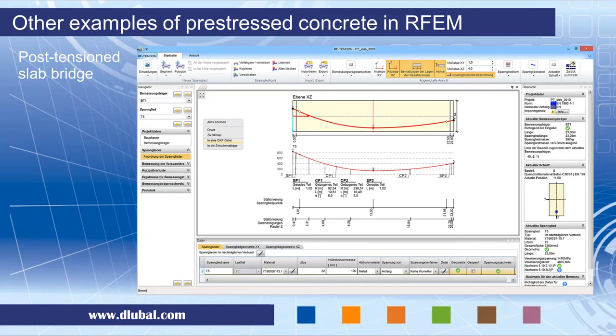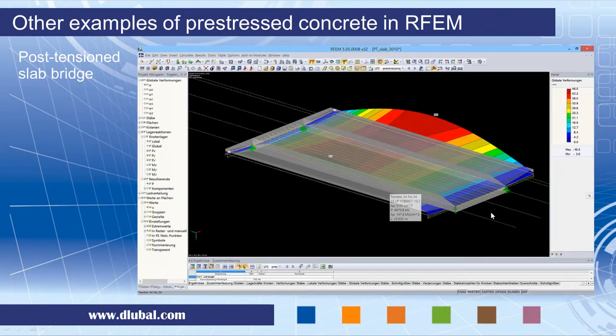So of course, in each of these result beams we defined such tendons. I defined it exactly according to that textbook, and then we can get the results back in RFEM. This is the effect of pre-stressing and the upward deflection, and this is the view from the bottom of the bridge.